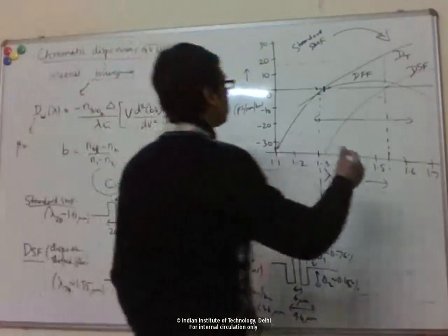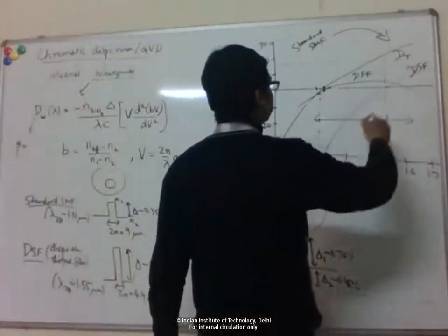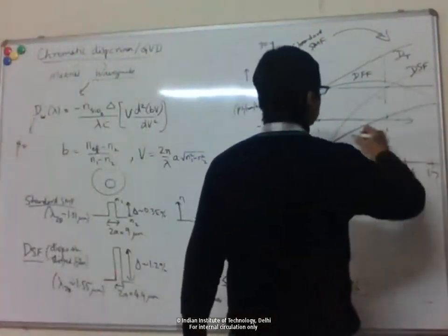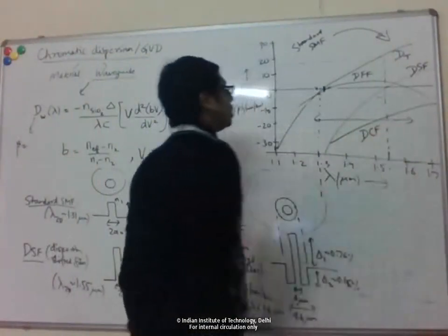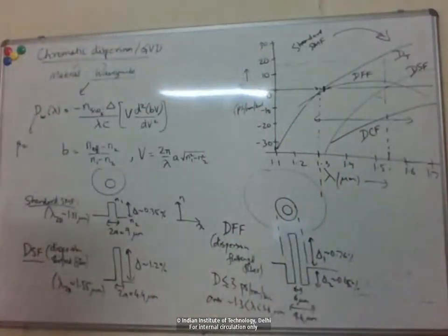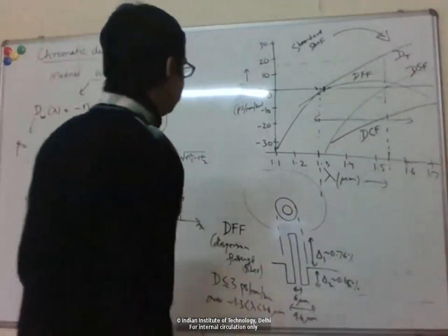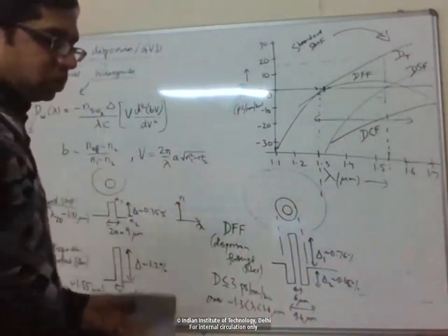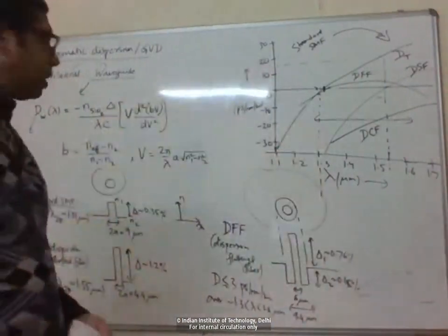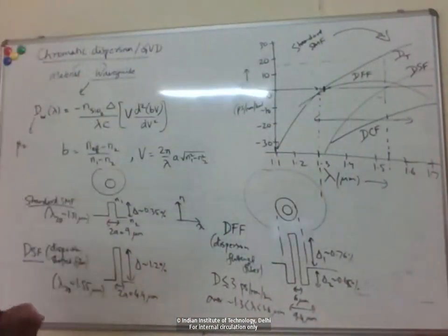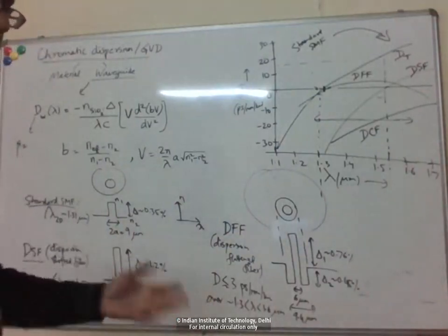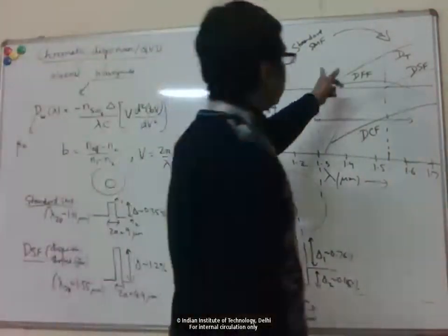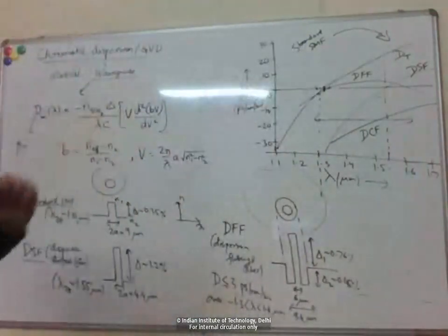So there is something called dispersion compensating fiber, which is even more shifted. It always looks negative, normal dispersion like this. Okay, so that's called dispersion compensating fiber. Basically, most of the long distance part of the link is standard fiber, right? And then near the receiver part, you can lay down a few meters or few kilometers of these other types of fiber to compensate for the dispersion, right?